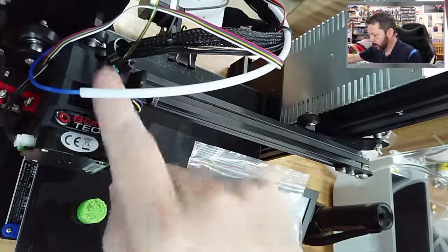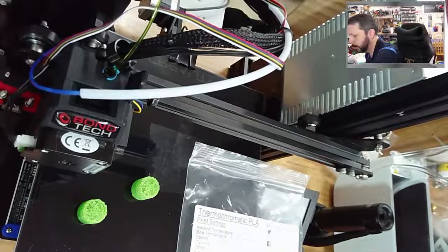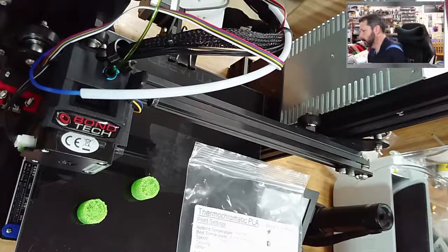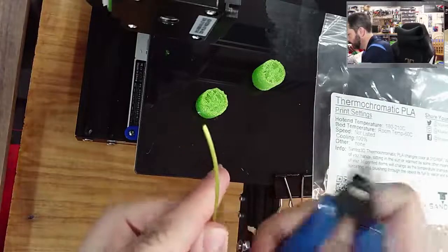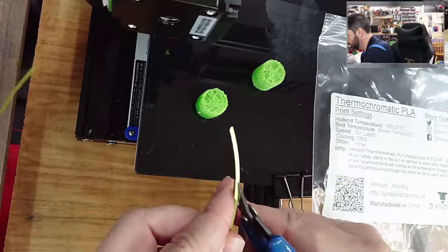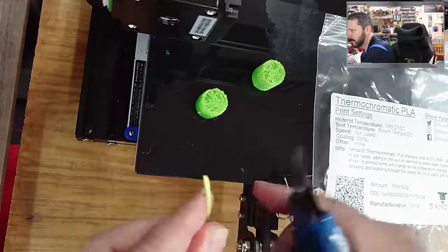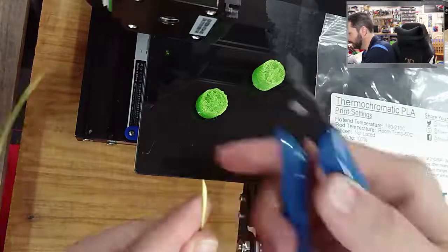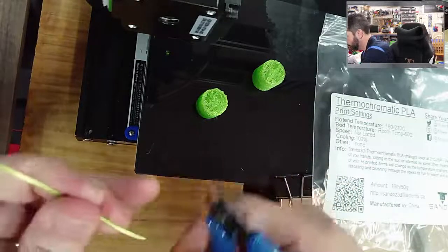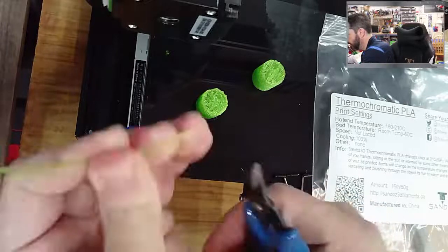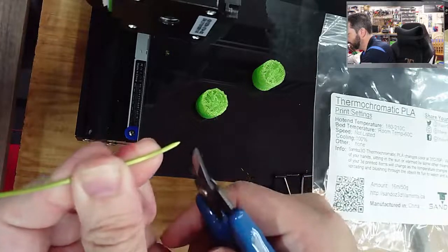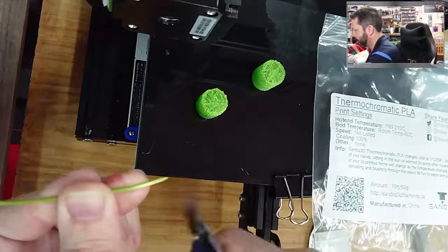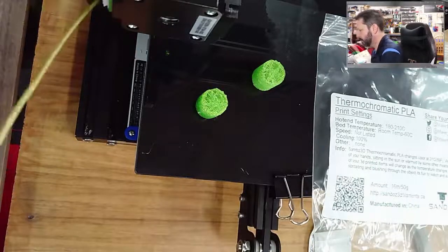last time I had a lot of trouble getting it loaded. What I ended up doing, I'll show it on this. This is not TPU, but it's stuck in there. So what I ended up doing is I did this kind of cut. This is what I normally do with PLA, is make a really sharp point there. That was not working with the flexible stuff. So I also cut from the other direction and made a point from both sides, so that whichever side of the hole it hit, it would probably go down in there. And that's how I ended up getting it to finally load.